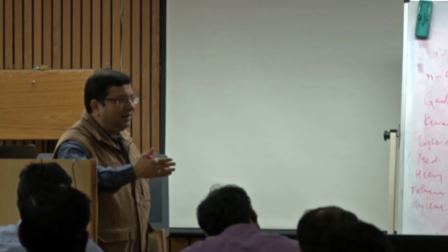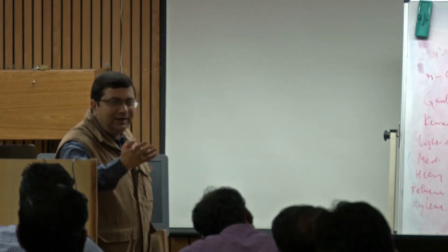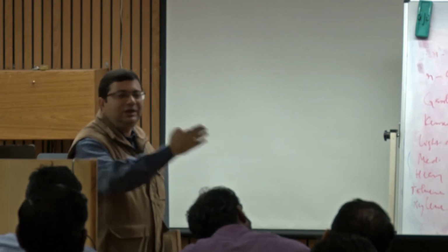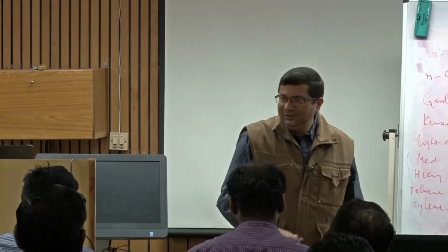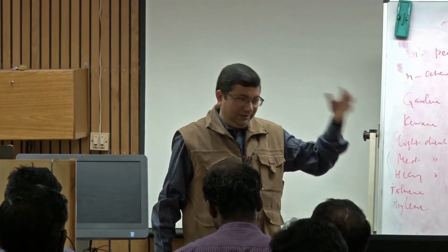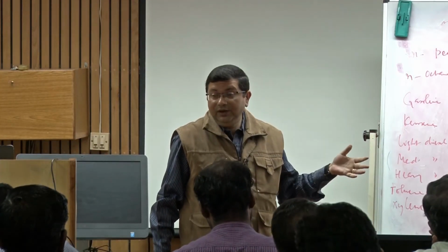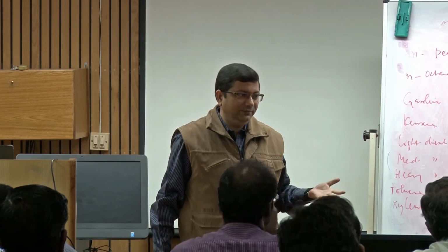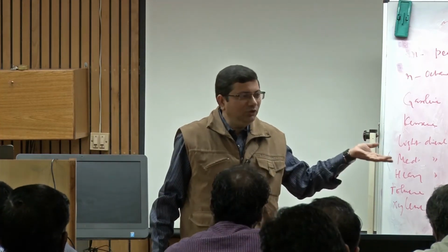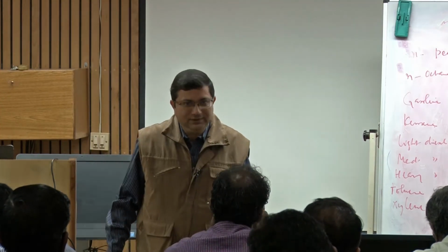We can test atomizers with water, and then from the droplet size we are measuring, we can infer what will be the impact on combustion, right. So, that is a huge advantage, because doing a test with the actual fuel is very dangerous and expensive, because we are creating fuel vapor, it may catch fire, particularly since most of the measurement instruments are laser based, right.